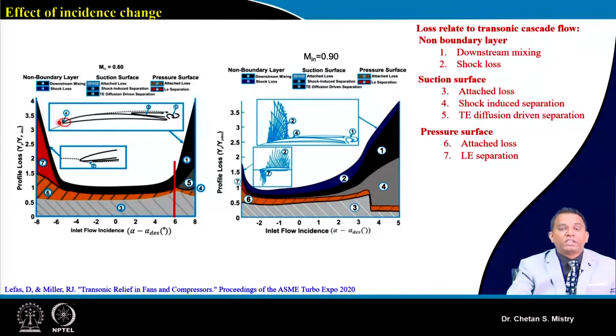Because we have this separation forming from this acceleration, it will be moving towards the downside. So in this particular region we will have the flow separation. Now because of this flow separation in the downside direction, our mixing loss is going to increase. We will have a thicker wake coming out.